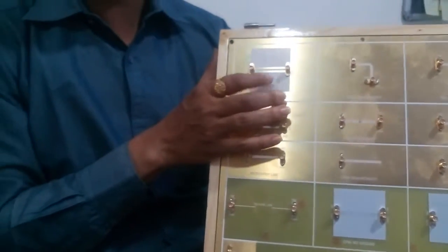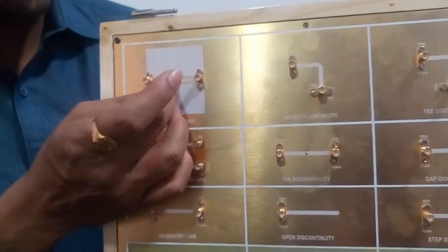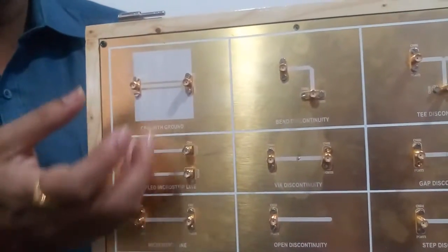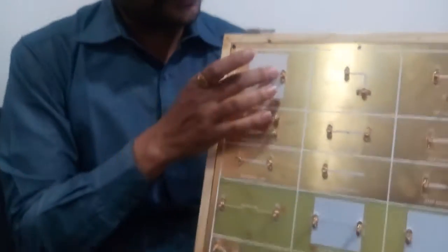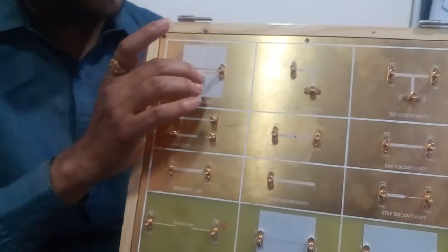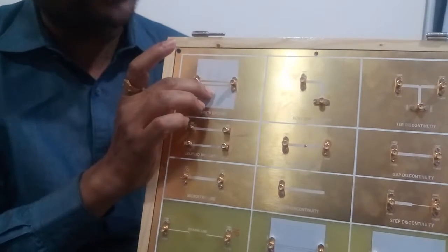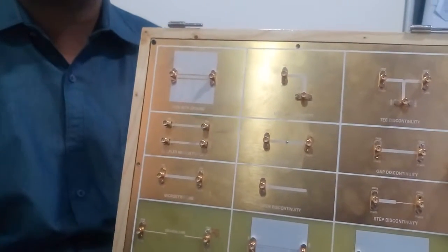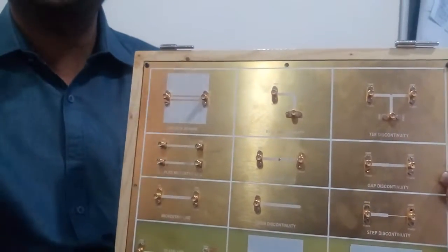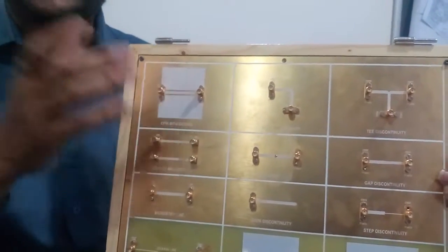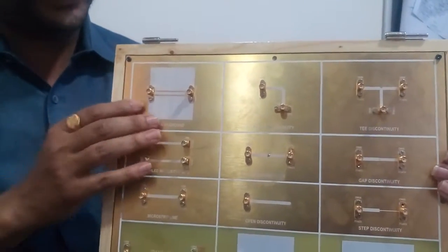Why is CPW popular in RF? Because many times you have to make sure that your components, coupling capacitors or transistors, have the nearest ground. If you provide it like this, this is the active line and this is the ground line, so you can connect your component easily between these two lines, and the component gets the nearest ground. If they fail to get the nearest ground, the noise floor of the overall device is going to be higher. This technology is mainly made for multi-layer RF circuits.